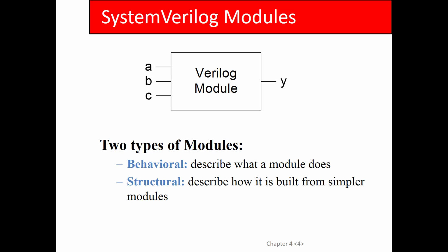So in chapters 2 and 3, you guys learned everything that digital logic hardware can do. Now the question is, how do you design large-scale systems? So behavioral logic is stuff that ultimately is a truth table or a state machine. Structural is when you have pre-made modules and you instantiate them and connect them together.